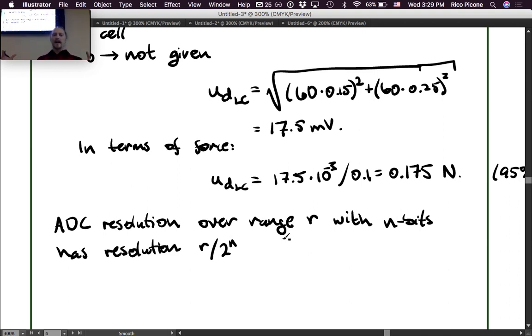So essentially you're dividing your range by the number of possible binary numbers you can represent in 12 bits. And of course you can convert a binary number to a base 10 number as well, so it represents just floating point numbers, right? So this is the resolution we have because that is the step size we can use to divide up that range from 0 to 5 volts.